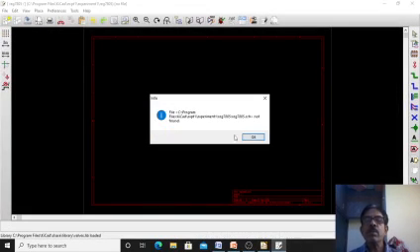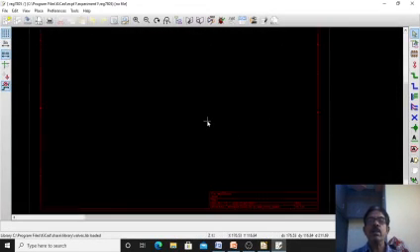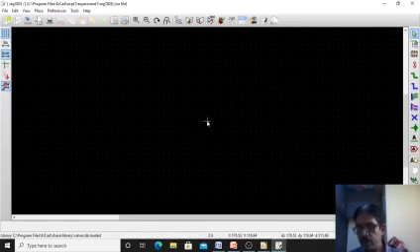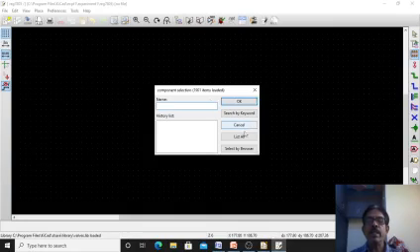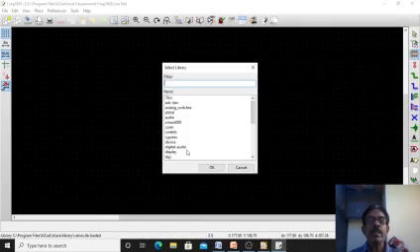An editor will come here. You can enlarge it using the mouse by rotating the wheel upwards. Then take the components. As we have seen earlier, the components are available here. It is called Place a component from the library. Click on that, then click anywhere here in the center, then List All. First I will take the regulator IC. It is in the library named regulator; you can search for REGUL.